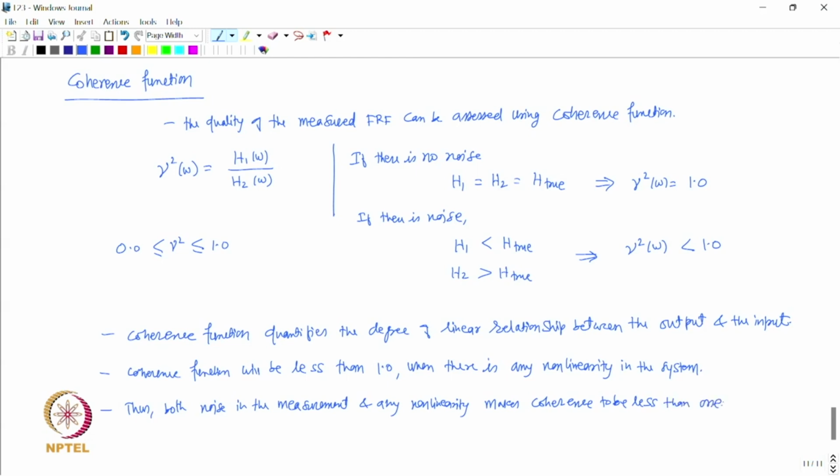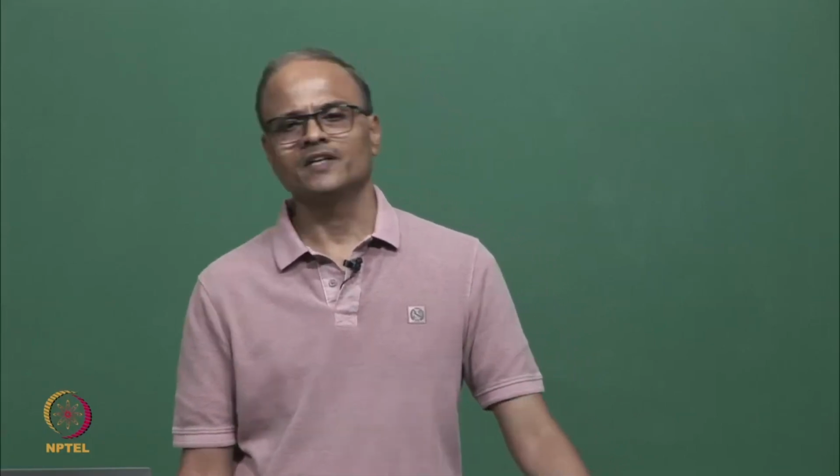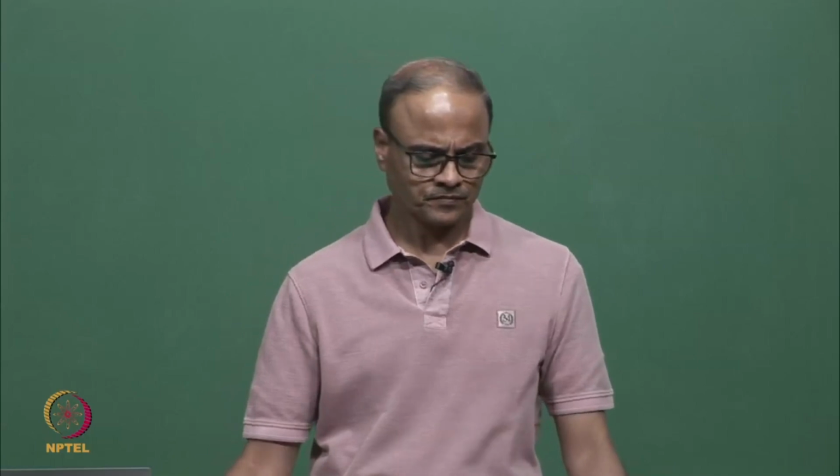Okay. So, in practice, for example, if the modal test is being conducted with a small amount of force, which is generally the case, then the non-linearities, even if they are present, will not be excited. So, in such cases, any drop in the coherence will be due to the noise in the measured signals, and the noise in the FRF will affect the coherence function. And therefore, the coherence function can be used to assess the quality of the measured FRF and to determine how much the FRF is being affected by noise in the measured signals.